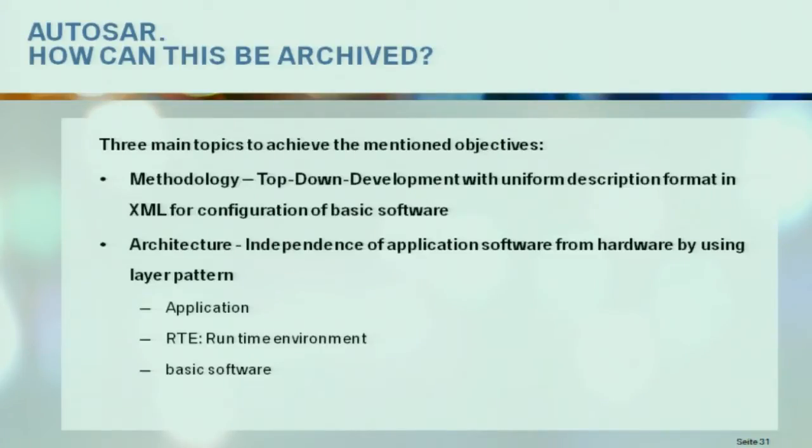And the last issue is standardized application interfaces. With this you can say we always have velocity as velocity or force as force, or moment as moment, but not as float, or as 16-bit float or 32 float.